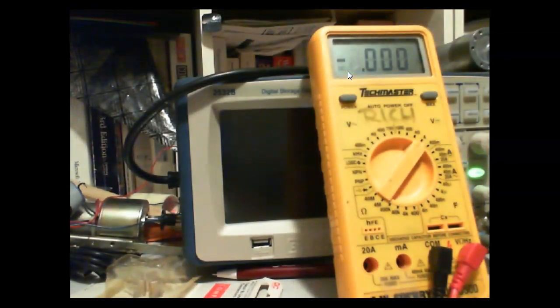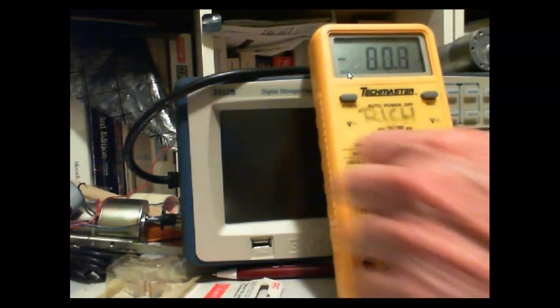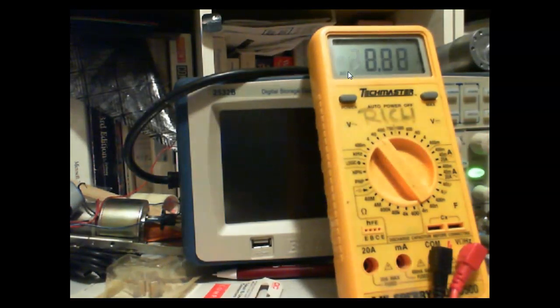This has got people killed, especially on these meters where you have to press a button to change between AC and DC, because normally it'll come up in one voltage level. So guys, you need to really, really be careful on that. Just because you measure 0 in something, you need to double check. If you're measuring an AC circuit, you need to put it on AC. So here's AC. This guy's putting out about 3.3 volts.